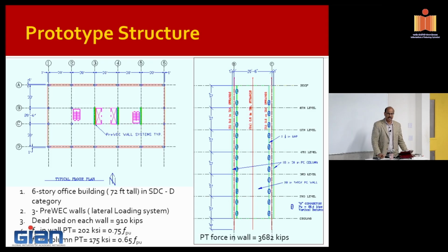If you put in a hysteretic damping, like through this energy dissipating element, this actually alters the velocity. So if you alter the velocity, the velocity dependent damping is now going to be different. So there's interaction between the damping also. One will affect the other one. So you cannot calculate everything separately and then sum the three to say, okay, this is my total damping. It doesn't work that way. So it's important that you understand where the damping is coming from.